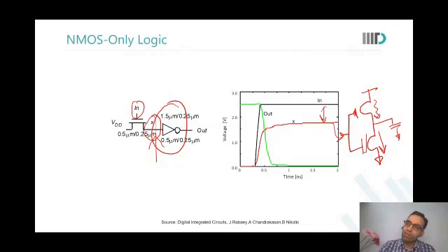Now the resistance of the just-off PMOS and the resistance of a fully on NMOS, that ratio is such that you're still getting an almost zero at the output. That is a different thing. But do you realize that there will be a very high subthreshold current flowing over here? Are you able to see that?